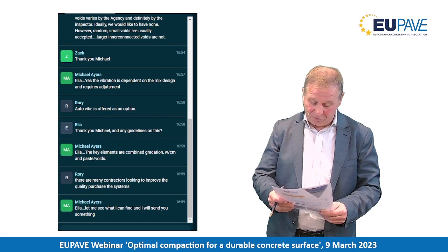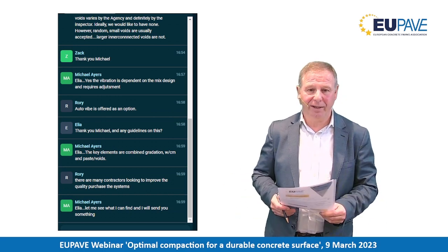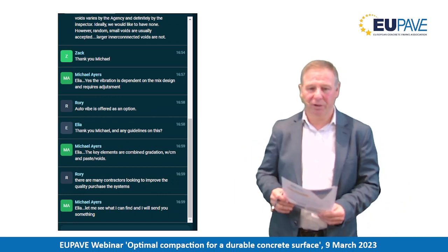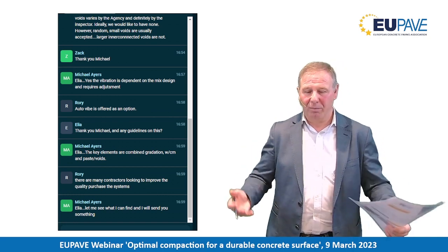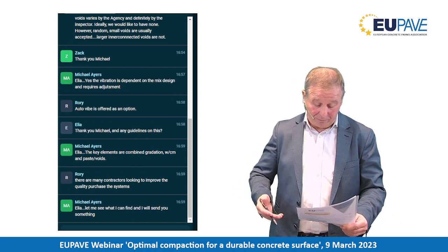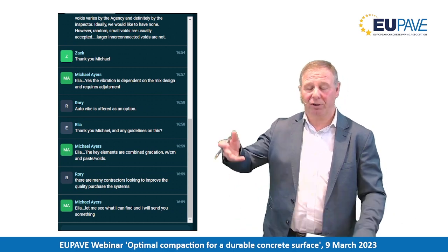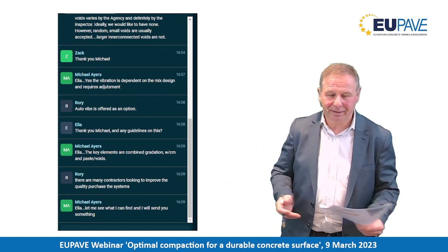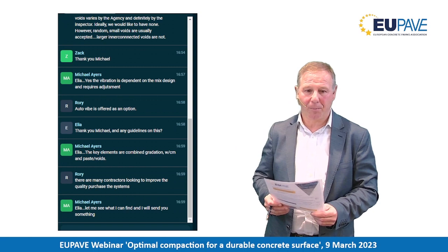So then also the question is, yeah, do we get to the same strength? And what about the thickness? Because of course, we're going to go to lower binder contents, lower thickness, and maybe lower strength. But if you have to compensate it in thickness, yeah, we will not really gain in carbon footprint.